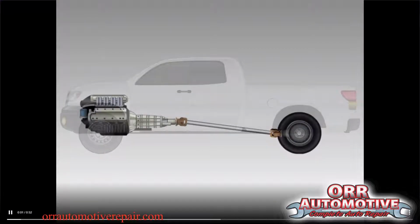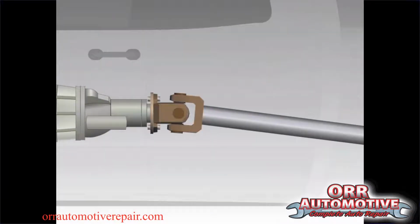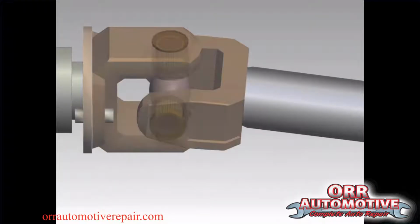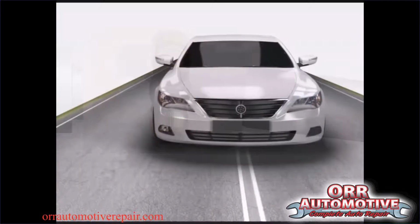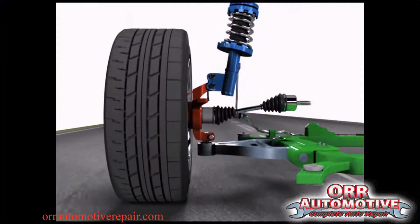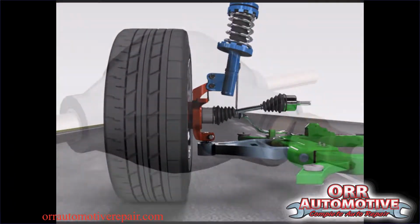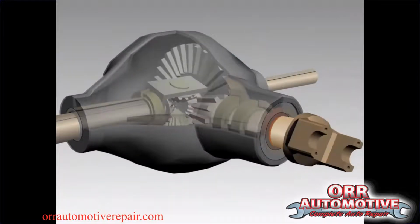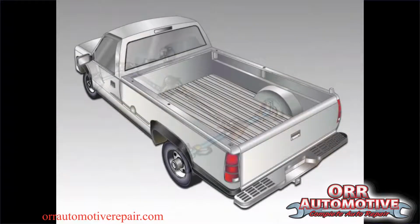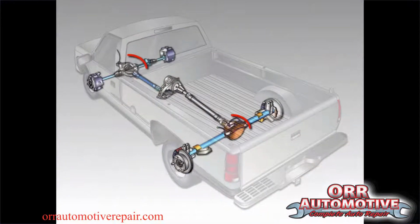Components of the driveline are designed to smoothly transmit the rotating power of the engine, while still allowing suspension to flex and wheels to alter direction. Front wheels are usually driven by an axle that includes constant velocity, or CV, joints. Differentials allow for the turning rate of a pair of wheels to be different, which is necessary during cornering. Four-wheel drive vehicles have two differentials, one for the front wheels and another for the rear wheels.